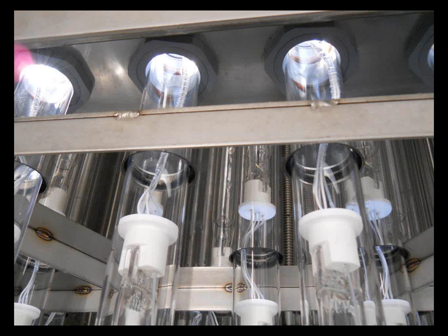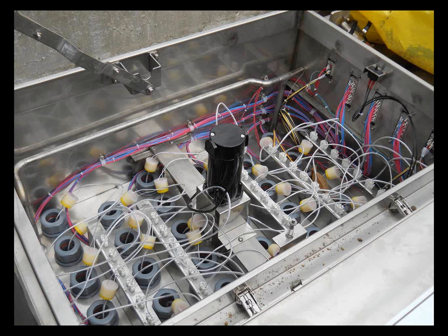This is a close-up look of the quartz sleeves with the bulbs in them. Looking down from the channel, looking up towards it, again, you see that it's very simple. These sleeves just slide right down over the bulbs and can be taken out one at a time while the flow is going. Very simple process. This is looking down in the top of one of the UV modules. You grab the little white and yellow handles, pull the wire, and come up with the bulbs. You grab the bulb, unplug one wire, take the bulb out, slide the new bulb in, plug it back in, set it down in there, and you're ready to go. It's very quick, very easy, just a couple of minutes in and out.